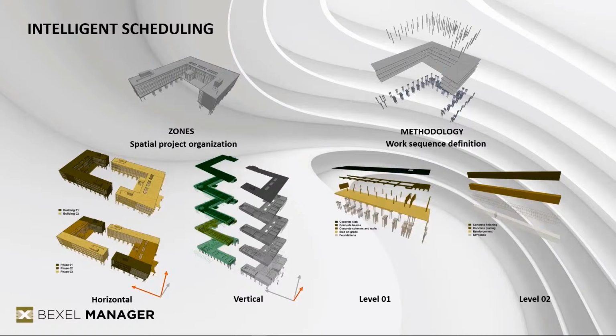Another one is work sequence, where you define that, for example, you first go with the site preparation, then you go with the excavation. After the excavation, you're going to execute foundations and so on and so forth. This is something that you, with your intuition and engineering knowledge, do every single time when creating a schedule. And you're doing it for every building, for every floor, for every zone.